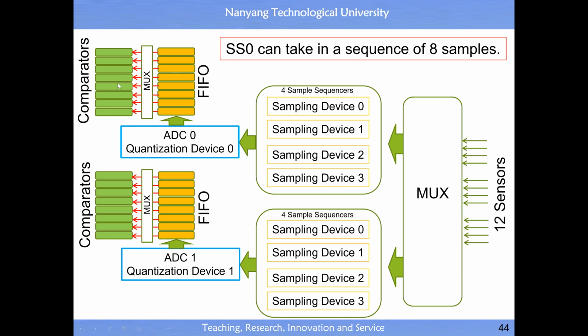So then he gives hardware support for you to do that. This is why you have a comparator. So this value goes inside the comparator, because each comparator will have 2 limit values, an upper limit and a lower limit. Hardware will do the comparison. If beyond that limit, it will send out the internal signal.